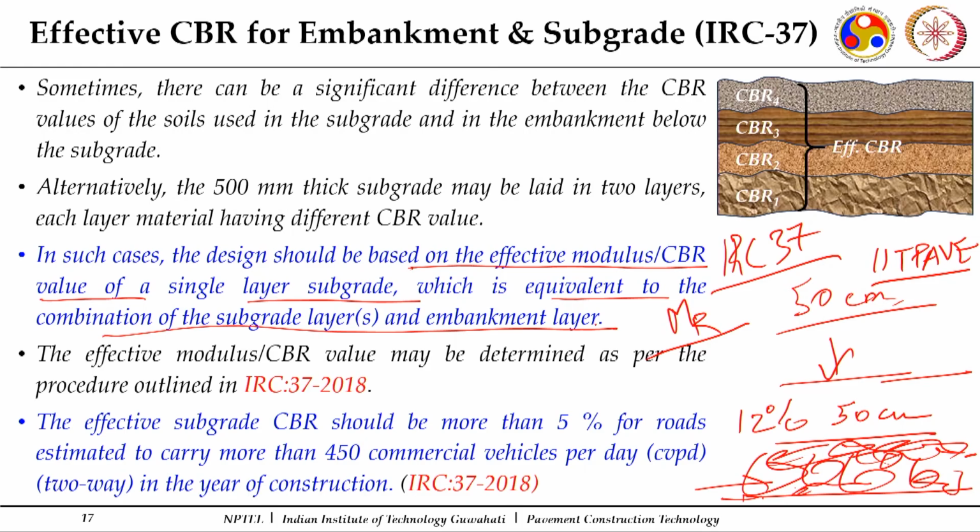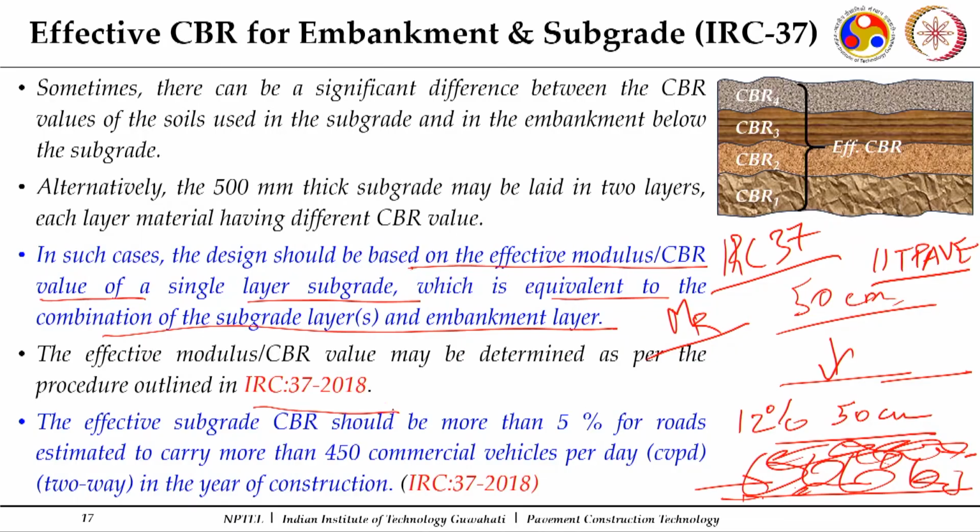So, you need to work out the effective CBR, which is a combination of the different layers of subgrade, or the subgrade plus your embankment, and this particular effective procedure is given in IRC 37. This is important to note that this is to be done.